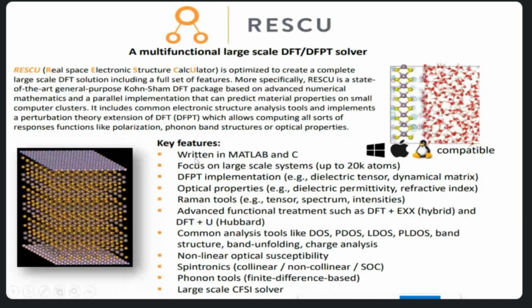So NanoDCAL can simulate 1000, 2000 atom based devices. But let's suppose you want to simulate 10,000 atoms, 15,000 atoms, 20,000 atoms. For material simulation only, Rescue can do that, but it cannot simulate the device. These are two different tools. One is called NanoDCAL, which is DFT NEGF for device calculation along with material as well, and Rescue is a DFT and DFPT solver for material simulation only, for response function, Raman property, optical property, and large number of